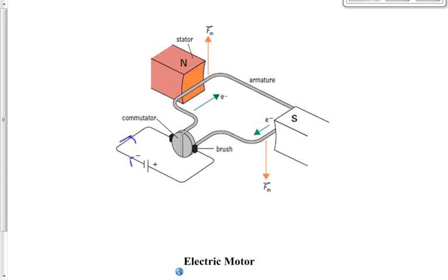This electric current goes through this wire and goes through this conductor that we call a brush. This little black block thing there. It's a brush. And this brush is touching this thing that we call a commutator, which is also a conductor. It's touching it. It's not connected to it. It's not fastened to it, but it's touching this commutator. This commutator is connected to this wire that goes around here that we call the armature.